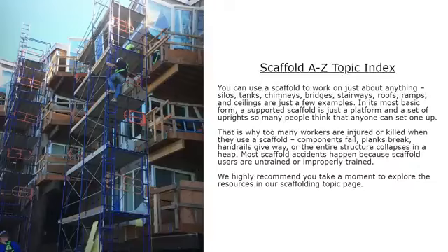In its most basic form, a supported scaffold is just a platform and a set of uprights, so many people think that anyone can set it up. This is why so many workers are injured or killed when they use a scaffold. Components fail, planks break, handrails give way, or the entire structure collapses in a heap. Most scaffold accidents happen because scaffold users are untrained or improperly trained. We highly recommend you take a moment to explore the resources in our Scaffolding Topic Index page.